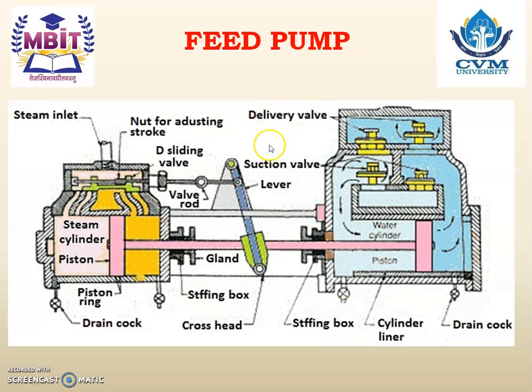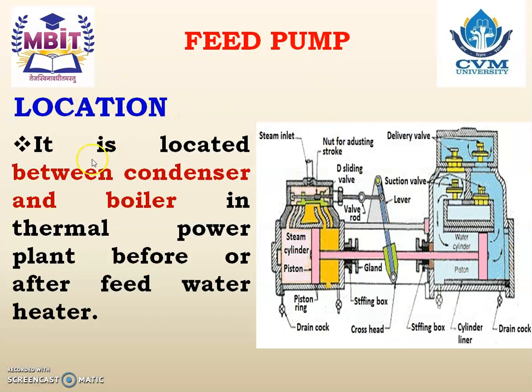The next boiler accessories that we are going to study is the feed pump. So the pump utilized to increase the pressure of feed water is known as the feed pump. Location. It is located between condenser and boiler in thermal power plant, before or after the feed water heater.